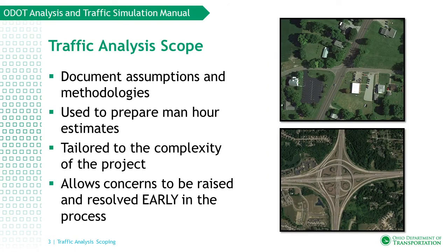The traffic analysis scope is the foundation for a solid traffic analysis. A properly prepared traffic analysis scope documents the assumptions and methodologies to be used for the analysis. It can also be used to help prepare the man-hour estimates for performing the work. The traffic analysis scope should be tailored to the complexity of the project. A simple rural intersection would be scoped much differently than an urban interstate with a system interchange.